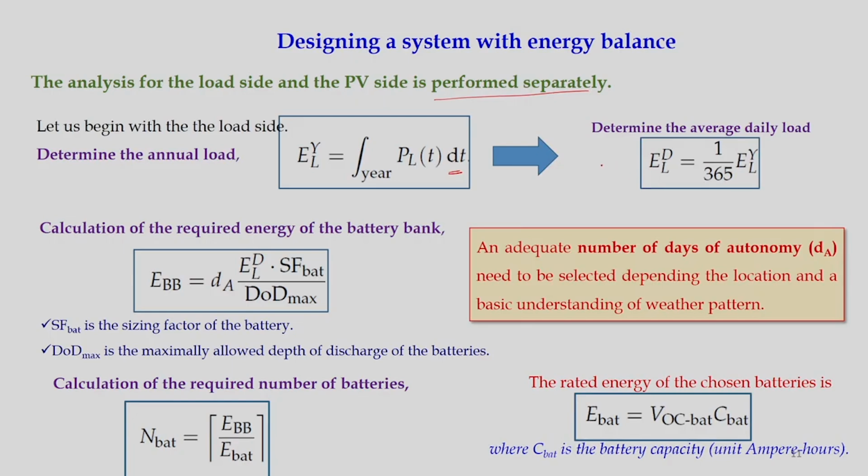So, E_LY will give you the daily load. Then what we are interested in is the calculation of the required energy of the battery bank. Once it is done, from that we must know the amount of energy to be delivered by the battery. This much of load, the daily load, is there.